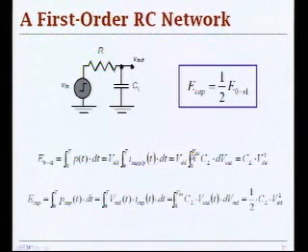That was your V infinity, or T in this case, where T is rather large. And then you have C times VDD squared. This is a very important relationship that you will find: the amount of energy that is injected from this source into your network is CV squared. So it's a quadratic function of voltage. And obviously, if you are a power conscious designer, you would like to reduce your supply voltage as much as you can, because that's the most dominant variable in your energy optimization.